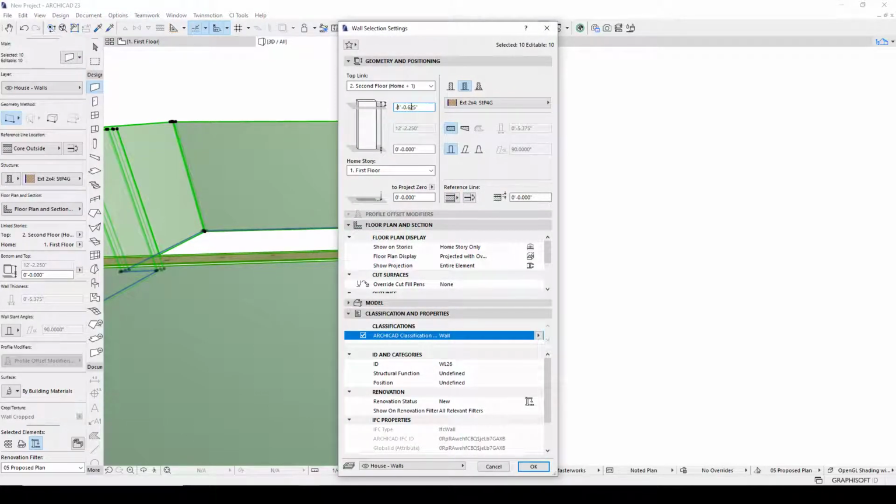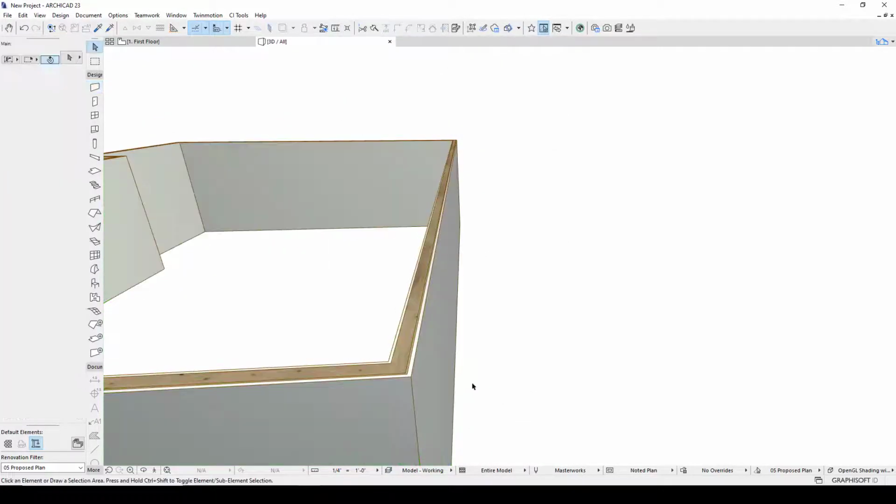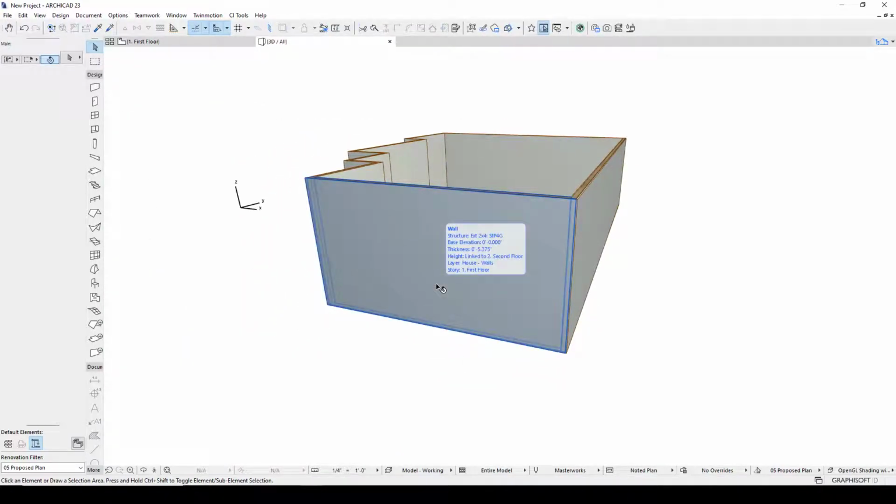Other thing to note is at Masterworks, we use decimal inches. I encourage you to do the same. I know a lot of people are going to think I'm absolutely crazy to do so. Let me give my rationale. When everything's drawn exactly, the dimensions work nicely. If there's any round off error at any point, your dimensions start to act a little funny. When I see the precision of 3 decimals, it allows me to know that there were no errors made, that it's perfectly where it needs to be. And I like that because then I don't have to fight with it later.